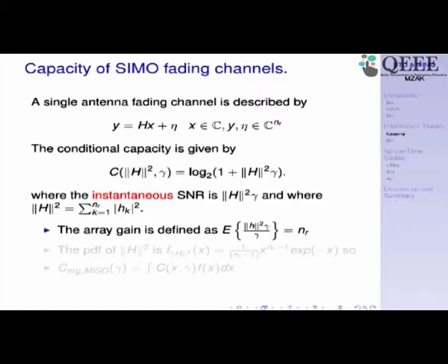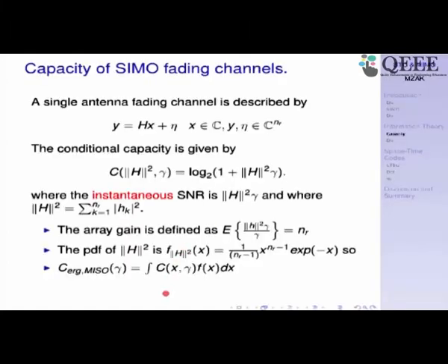Right, now going ahead, this capacity is again a random variable, where this is our random variable, the Frobenius norm of the channel matrix. So we need to average it out. So we need to find out the probability density function of the Frobenius norm. It is well characterized and it is basically given by this formula. It is called the chi-square distribution, with NR degrees of freedom. And then averaging out using our expected value summation, this is the final ergodic capacity. Remember that we are discussing an ergodic channel, so it is varying every channel instant, so it is basically a fast fading channel.